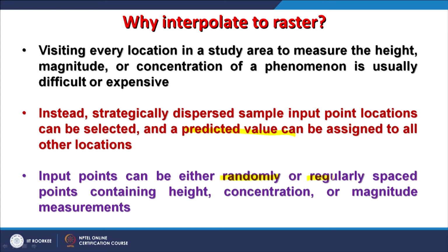If you are not having regularly spaced points, which are near impossible, and if the points are, say, within one topo sheet located only in one corner, these spot heights, and you employ that for a spatial interpolation, you may get very poor results regarding accuracy.